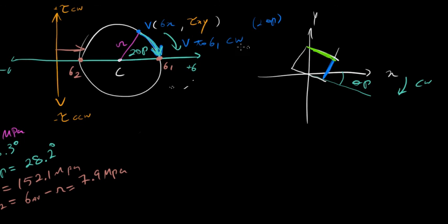So in relation from the vertical face to sigma 1, we went from here to there in a clockwise fashion, and that principal stress is in tension, a positive number on the positive axis. We already calculated that. Whatever that is, sigma 1 is acting on that vertical face, from here to there.